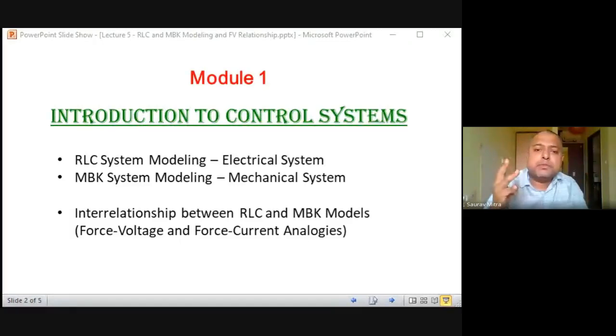Third, from the characteristic equation we are supposed to find the poles of the system, that is, the roots of the characteristic equation. And fourth, we have to find the pole position, the roots of the characteristic equation. We have to see whether the poles have negative real part or not. If the poles have negative real part, that means they are stable poles. Stable pole means what? If the system is stable, what does that mean?